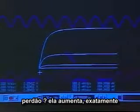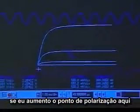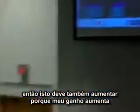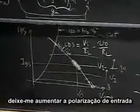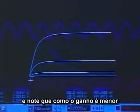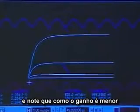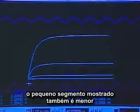Pardon? It increases, exactly. If I increase the bias point to here, then this must also increase because my gain is increased. Okay, let me do that. Let me increase the input bias. You indeed notice that the region of the load line articulated is larger now. Let me decrease the bias, and notice that because the gain is smaller, the little segment shown is also smaller.